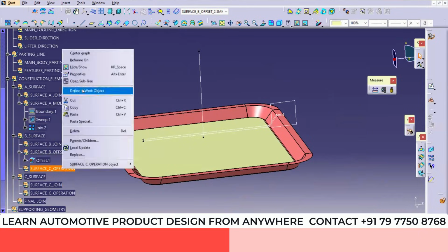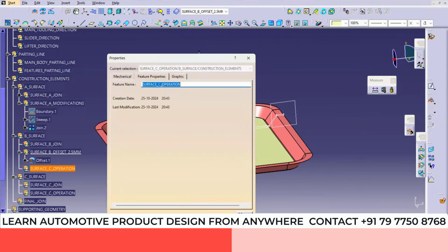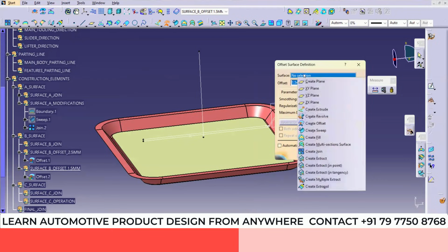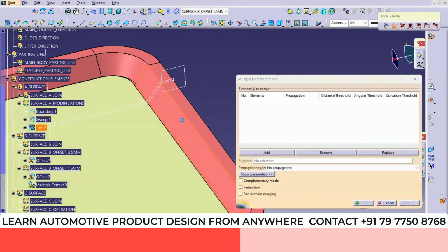For the B surface, offset 1.5 mm. Now define this. Offset 1.5, right click, create multi extraction, and then select this.